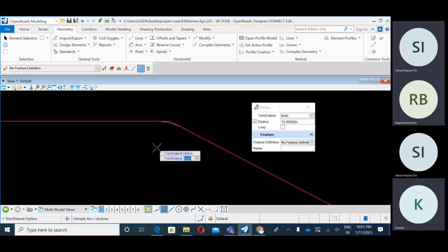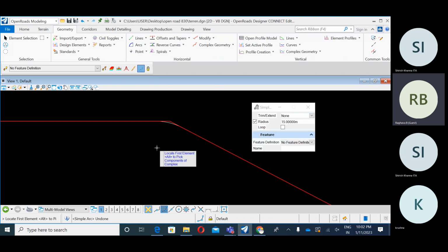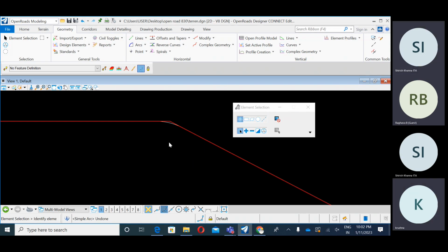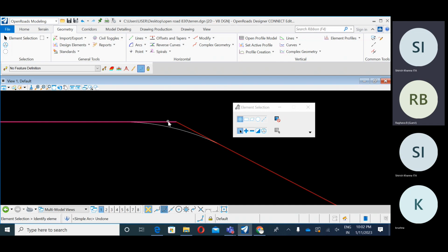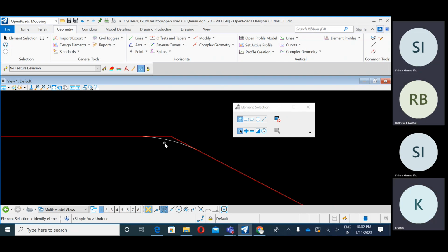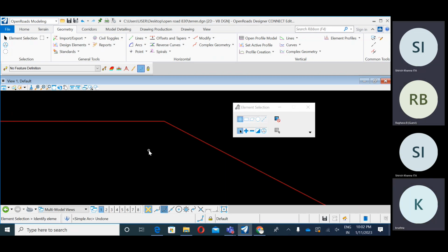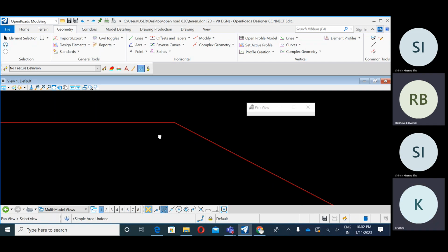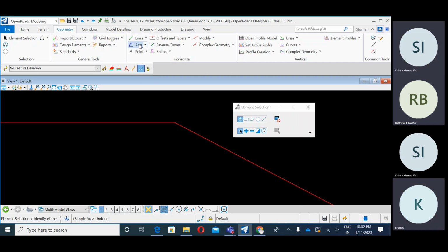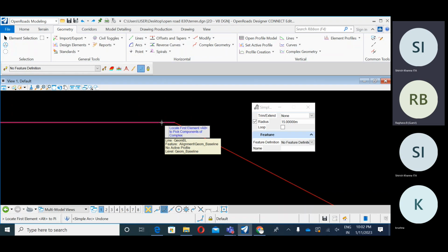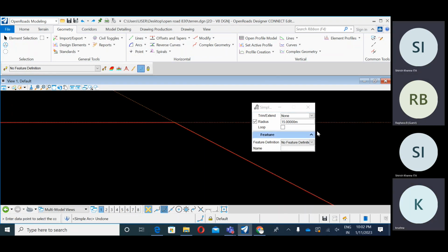Now you can change the value here also by using arrow keys: both, none, back. If you want both lines to stay the same, go for none and left click. See, we get the same portion, fillet also. Similarly, we are going with ahead. Okay. So go to the arc, first, second, and if you are using 15, that's okay.